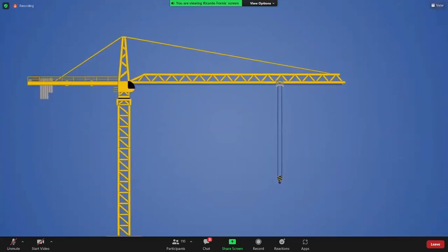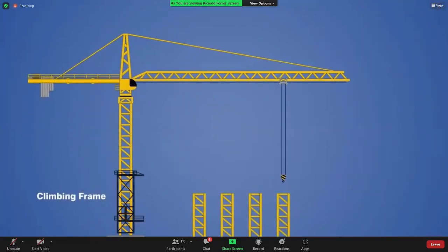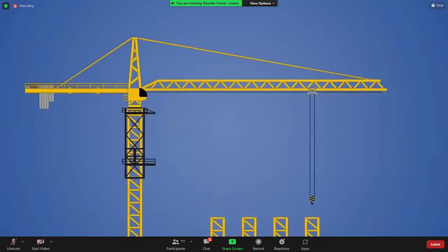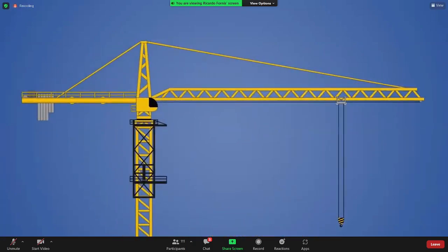When a tower crane is ready to be climbed, a steel climbing frame is first assembled around the base of the tower, and it is lifted up to the underside of the slewing unit. The frame has a square cross-section with a lattice structure around three sides, but the front is left open so that new mast sections can pass through. The top is securely fastened to the underside of the slewing unit with high-strength steel bolts, and a hydraulic jack at the bottom is positioned over a push point on the existing mast.